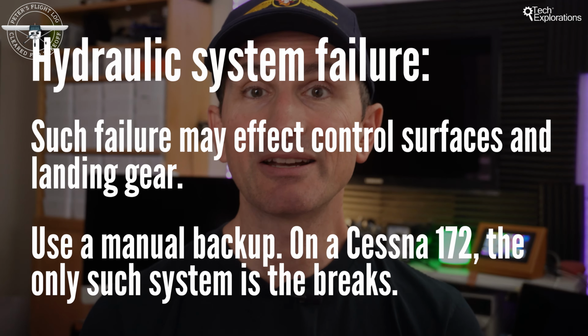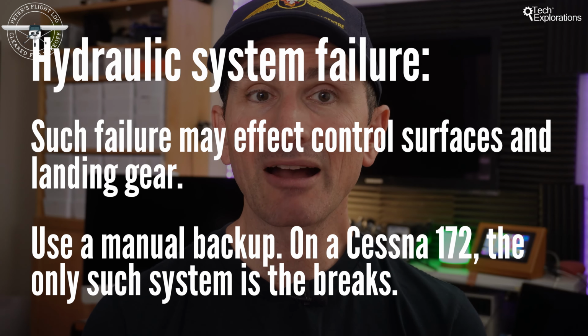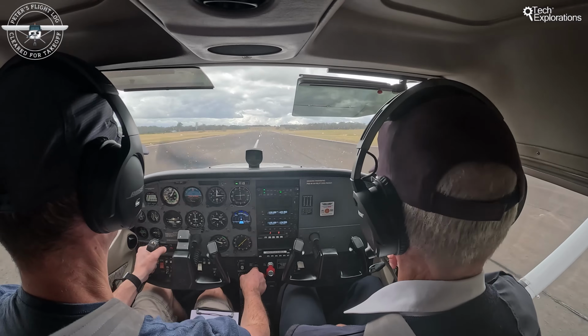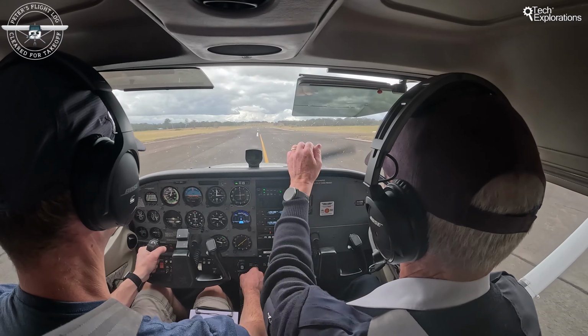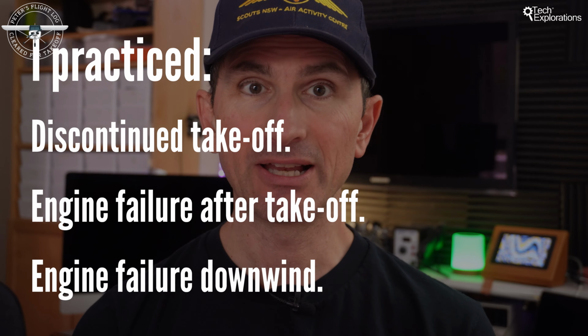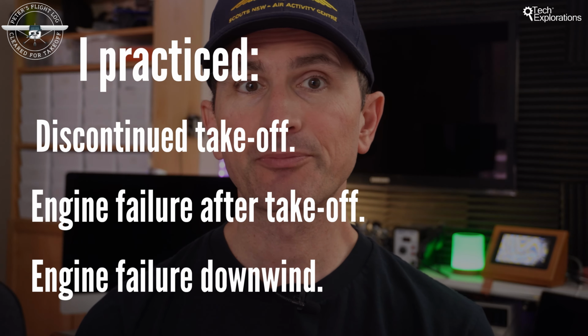Hydraulic system failure. A failure in the hydraulic systems affects control surfaces and landing gear. Manual backups or alternative procedures are initiated to land the aircraft safely. In the Cessna 172, the only hydraulic system is the brakes. All other controls are operated by cable and are not assisted by hydraulics. Again, that's one less thing to worry about. On this flight, I practiced the discontinued takeoff, engine failure after takeoff, and engine failure downwind. Let's have a look at the video starting with discontinued takeoff.